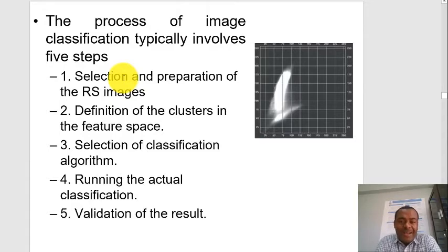For example, we have seen Landsat with different sensors. You have to be able to select the appropriate remote sensing image even from Landsat. Do I use Landsat TM image? Do I use ETM image? Do I use OLI image, Landsat 8? Or shall I jump into a Spot program satellite? Or shall I use European Space Agency satellite programs image? Or what shall I use? These are the kind of things that need to be discussed first before you go to your image classification.